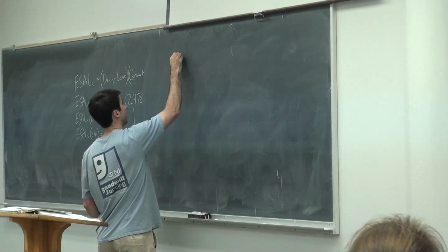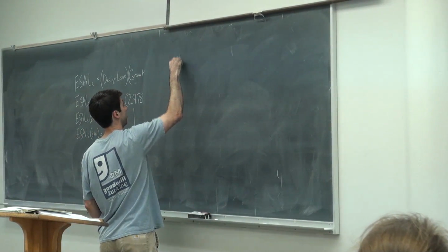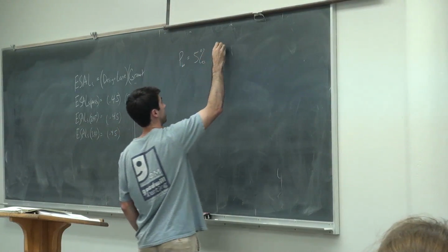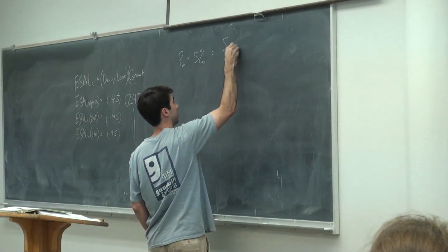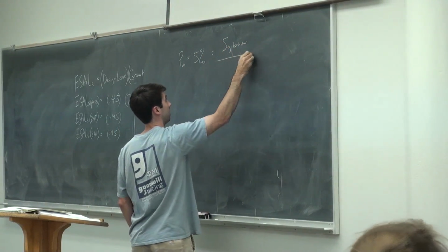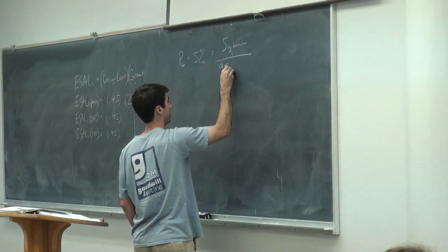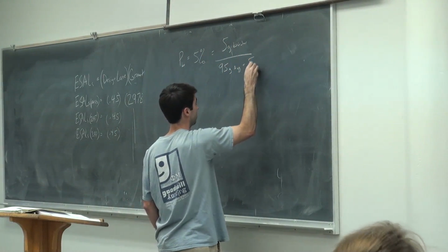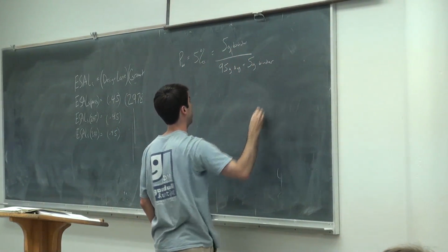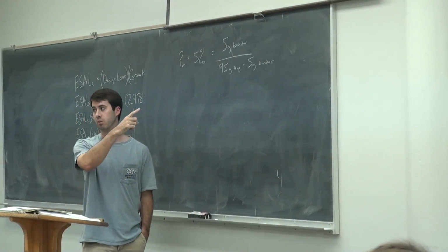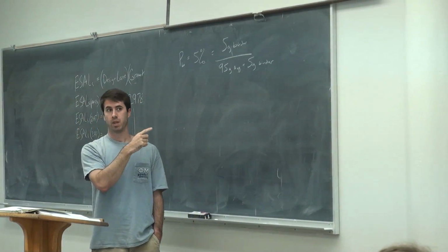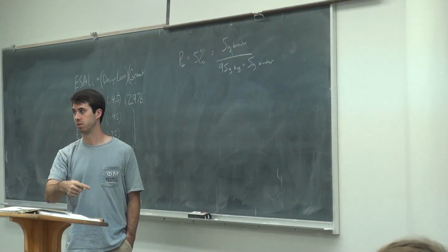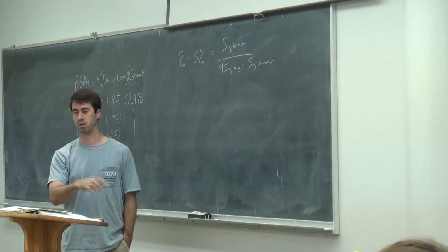Basically, if you say you got a percent binder of 5%, that means 5 grams binder and then 95 grams aggregate plus 5 grams binder. If you take that the other way, like aggregate absorptions, they're based on the aggregate mass, not the combined mass of the aggregate and the water.